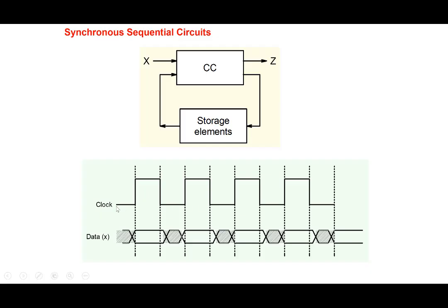And the idea of a clock signal is that it synchronizes everything in the circuit, so everything takes place in sync with the clock here. And so the idea is that if you have a combinational circuit, we know that the signals may come at the input of the combinational circuit with different amounts of delay. And not only that, there's a feedback also. And unless we take care of all the delays that are there in the circuit, we may end up getting wrong values at the output.